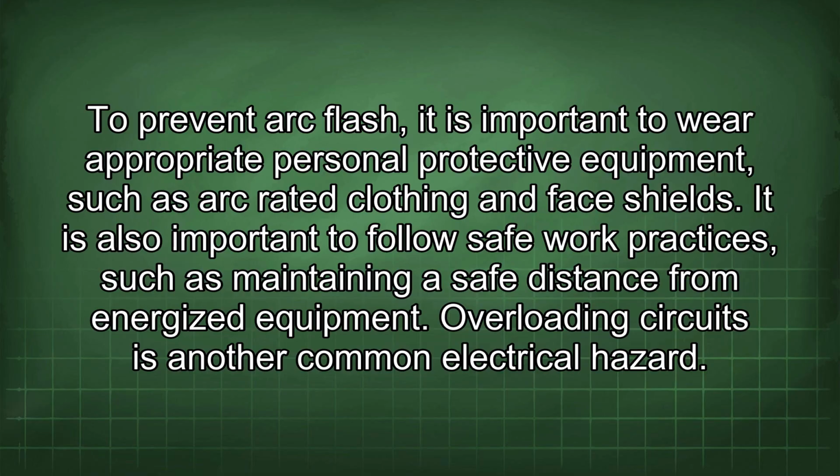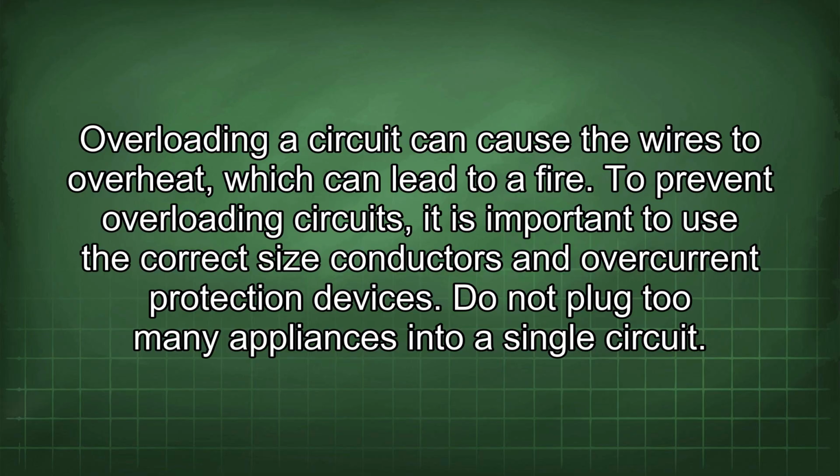Overloading circuits is another common electrical hazard. Overloading a circuit can cause the wires to overheat, which can lead to a fire. To prevent overloading circuits, it is important to use the correct size conductors and overcurrent protection devices. Do not plug too many appliances into a single circuit.